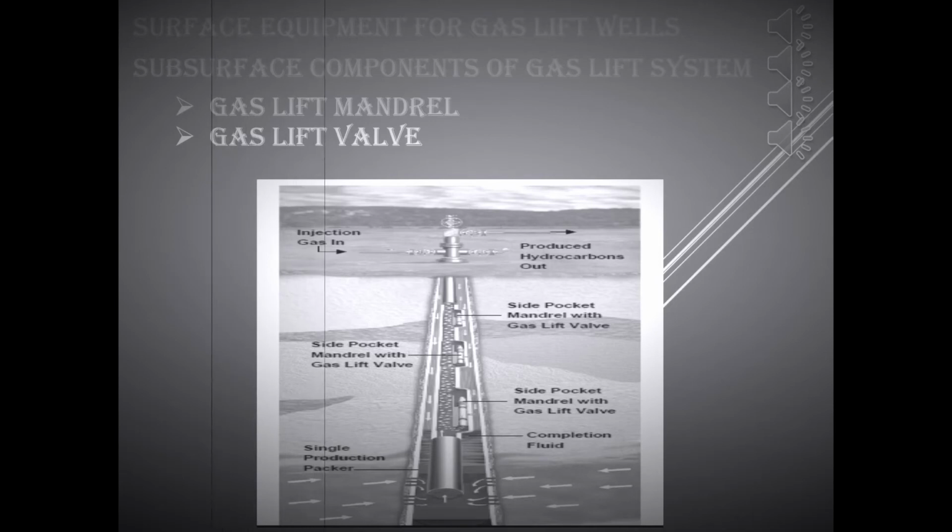The outer shape of the mandrel's tubing body looks oval-shaped, with its eccentric end having box tubing connections. It has a pocket welded inside it in the eccentric portion, which is intended to house the gas lift valve. The pocket has drilled holes to connect the pocket bore with the tubing, that is, with the mandrel, and separate drilled holes to connect with the inside of the tubing. The eccentric form of the mandrel is required to ease the wireline job for the selective setting and retrieval of the gas lift valve.